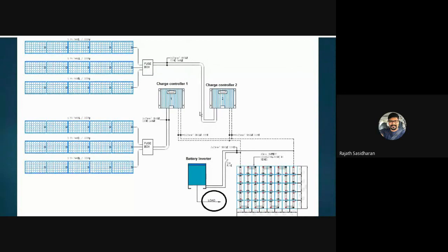So this goes to a charge controller here. In this system, which we actually built, you can see 2 charge controllers in action. So they must sync with each other. There is a communication between these charge controllers. It can be through hardware or through Bluetooth, depending on the manufacturer, because these two charge controllers must sync to make sure that the terminal voltage and the charging algorithm are in action in a proper way. So from the charge controller, it goes to the battery bank.